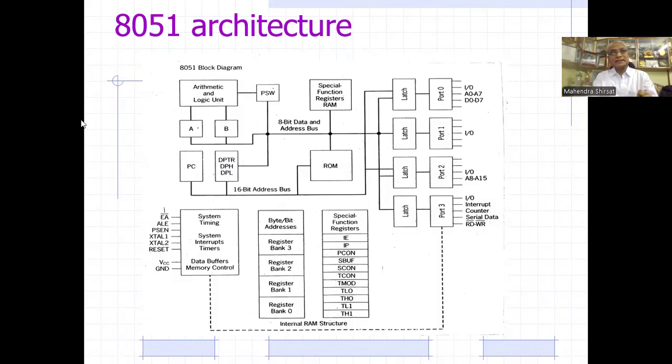But then what is the need for register B? Whenever we are doing addition, let us say 05 plus 06, 05 can be transferred to the accumulator, and 06 needs to be transferred to some other register. That register is going to be a temporary register, and here it is register B. So register B is a temporary register. A is the accumulator, a very special purpose register as far as the 8051 microcontroller is concerned.